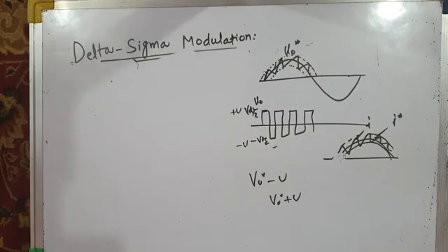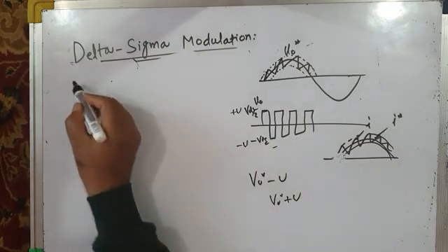No, we can, because in order to obtain behavior similar to that of hysteresis current control, it is necessary to emulate the integration effect of load. It's a very important statement, you note down.